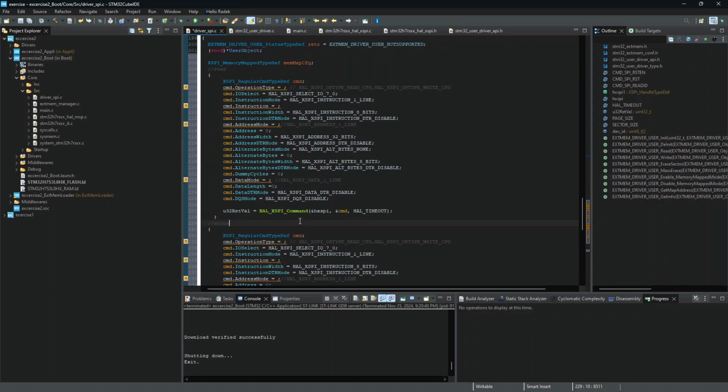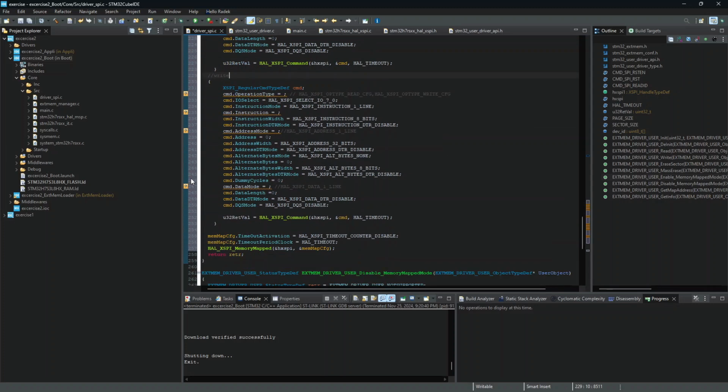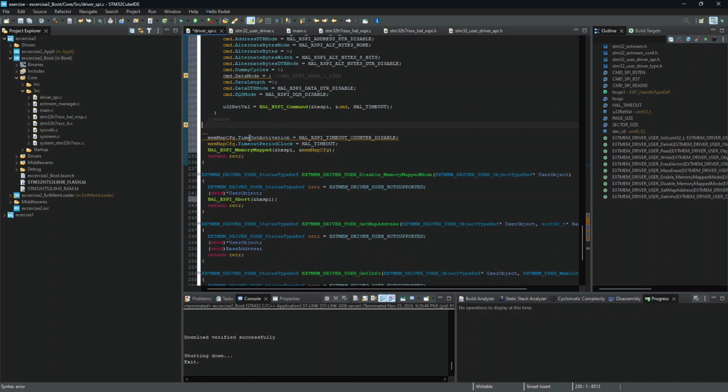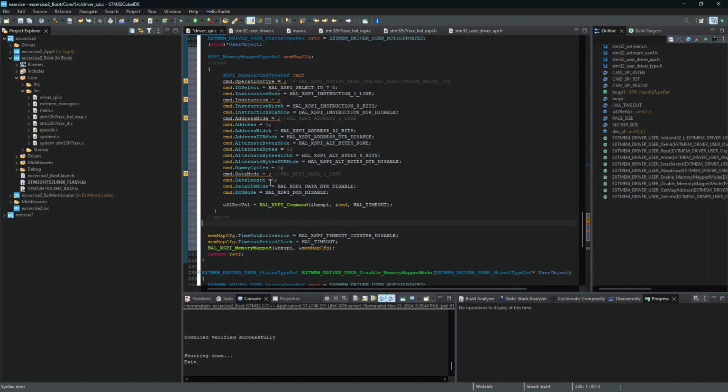Because I don't want to really write any information there, I can keep them completely the same. So this was maybe pointless. I can then copy this configuration, because we will not really write into the memory, because, as I will show you, the writing is more complicated and it's not possible to do by one command. This is possible to do with the RAMs, but with the flash it's unfortunately not possible.